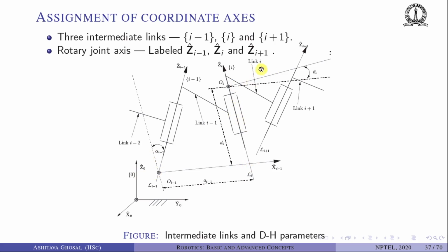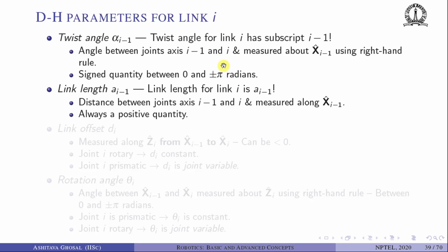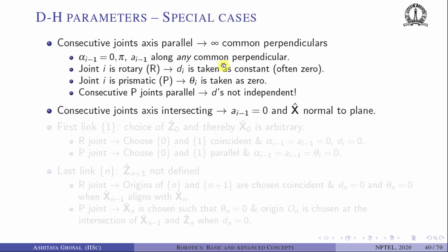How about the orientation of link i with respect to link i-1? There are two angles. Remember alpha_{i-1} and theta_i. So first I make a simple rotation about x-axis by alpha_{i-1}. Then I make another simple rotation by angle theta_i about z-axis. So these are the two rotations which are happening, and these are the two translations which are happening. These are the 4 DH parameters basically. Let's go back to the equation once more.